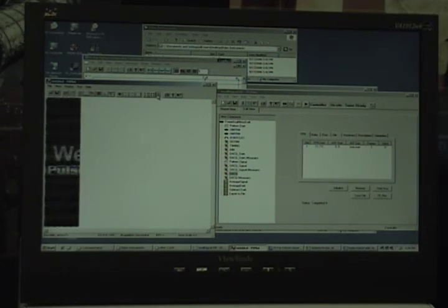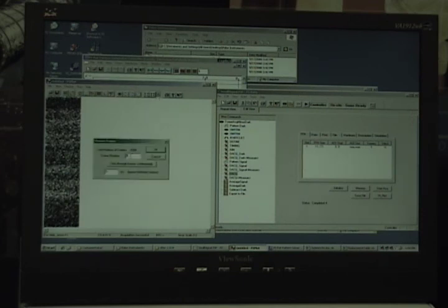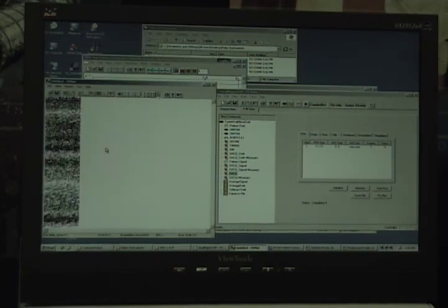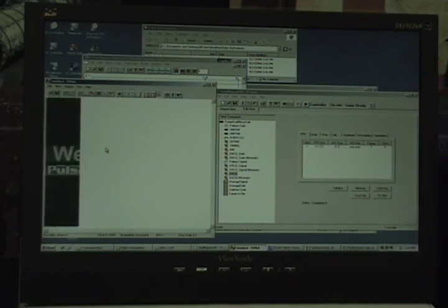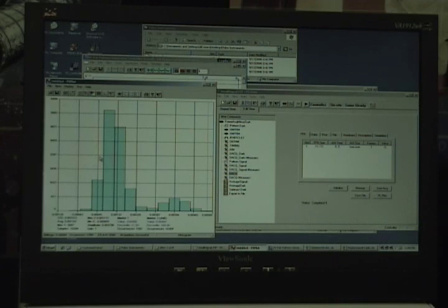The video file I'm showing you now has been post-processed so that frame n is the average from frame 1 to frame n of the original raw data. In other words, frame 100 is the average of 100 frames from the original data file. As we play through the file, we can see the random noise being averaged away as more frames are averaged, and the constant signal comes through. The difference between light and dark is 6 microvolts at the preamplifier input.